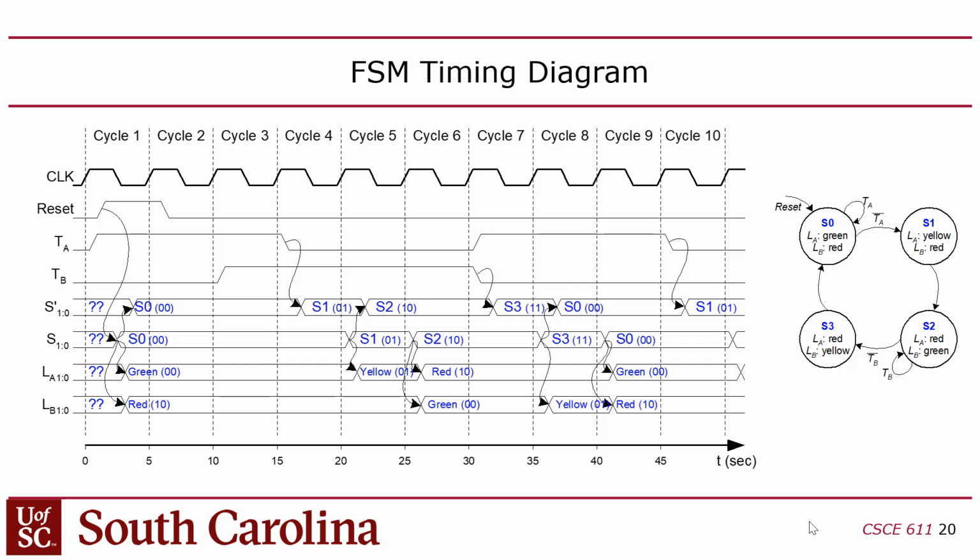You guys with me? Okay, so what happens is we start out in S0. We get some traffic on Bravado here, which is ignored, because that's how the circuit is designed. Traffic on Academic, though, goes from 1 to 0, and that's when we finally begin the transition to the green light on Bravado, but of course we have to go through S1 first. The yellow light state is S1 and S3. You'll notice that those are always one cycle because there's an unconditional transition out of there, right?